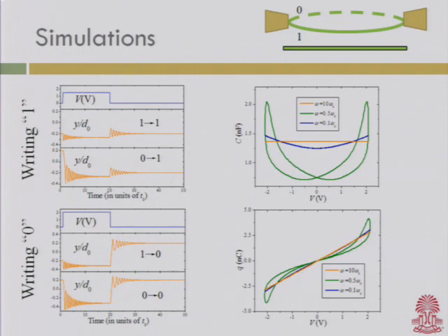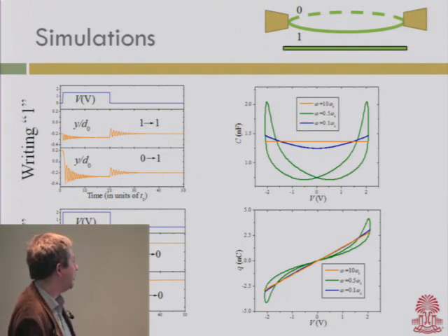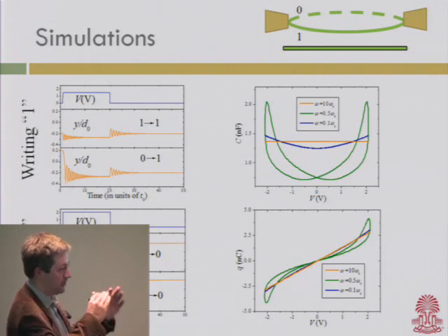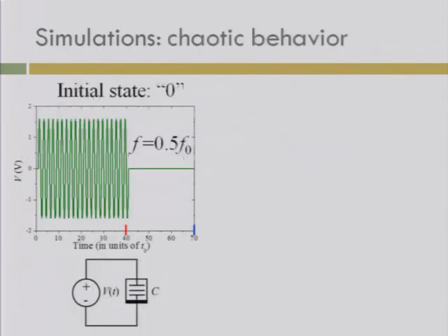In order to switch to the low capacitance state, we propose to put more charge on the plate, and after that we can just release, and the elastic energy conserved in the system can make the membrane move up. So we pull it down strongly, release, and so we can switch between the top and bottom state. However, this is not the most interesting feature.